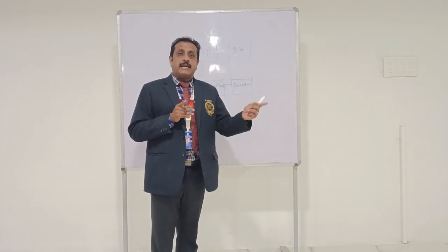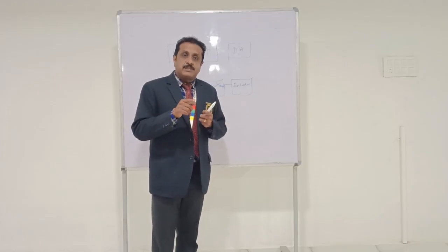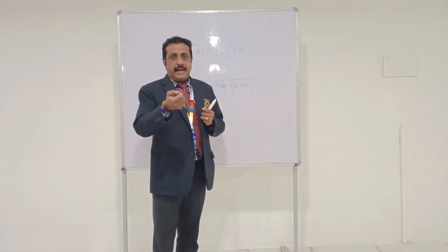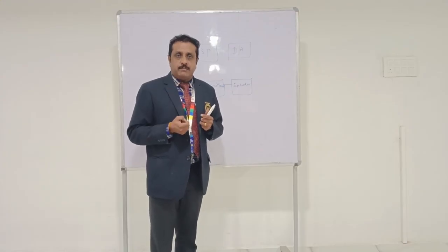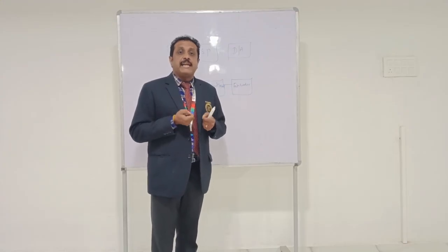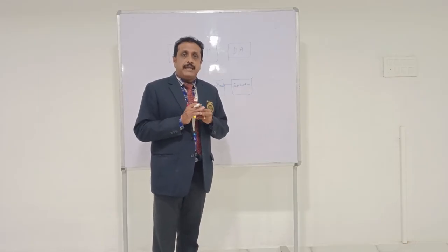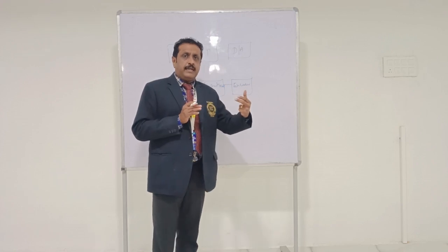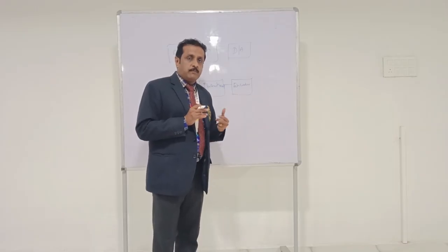But the setback of the DTFT is that omega is still a continuous variable. So we need to sample that omega. As a result, the final transform we derive is the DFT, discrete Fourier transform. By using this DFT, we can analyze discrete time signals.